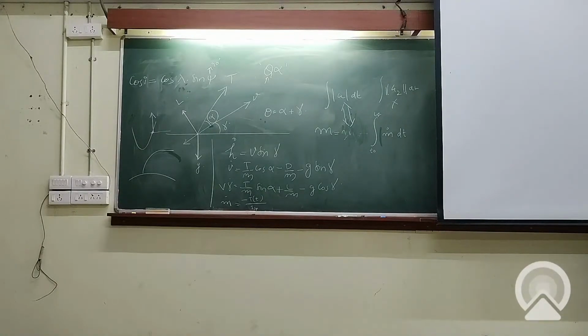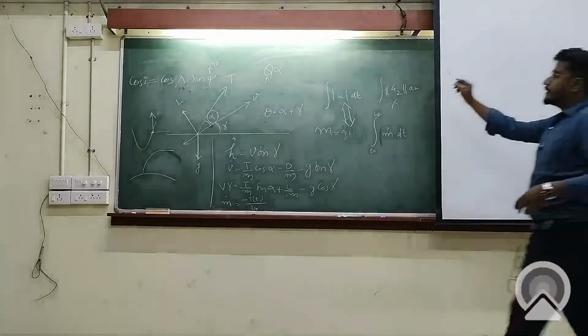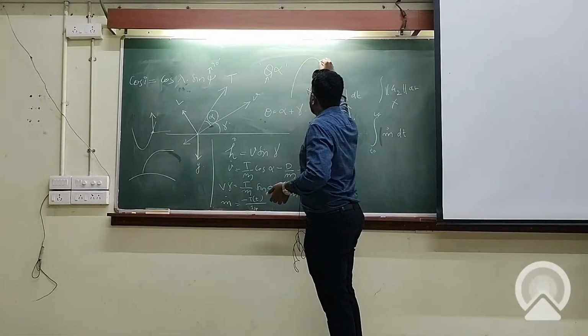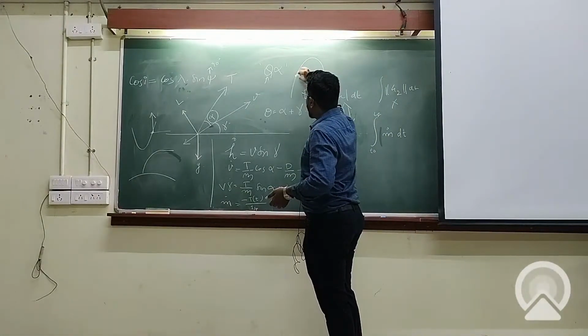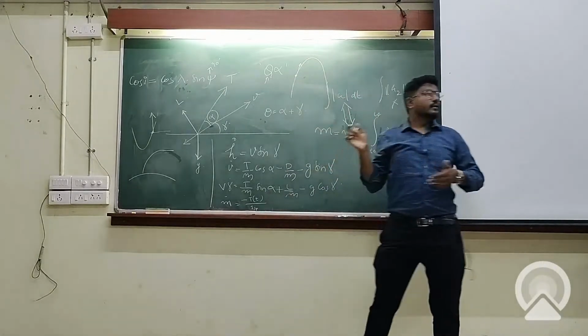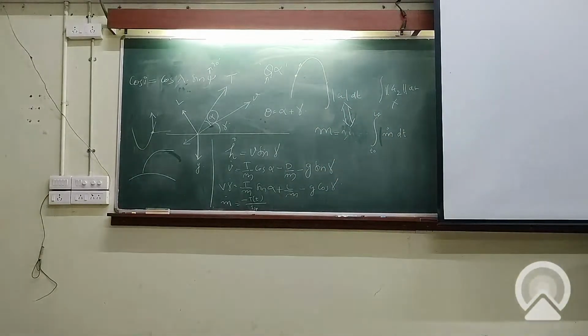You are traveling in a conic. Say the separation happened here, then you are simply ascending along the suborbital ellipse. Right. During that phase, your energy has to be conserved. So your kinetic energy is being converted to potential energy. Otherwise, at the expense of velocity, you are gaining altitude.